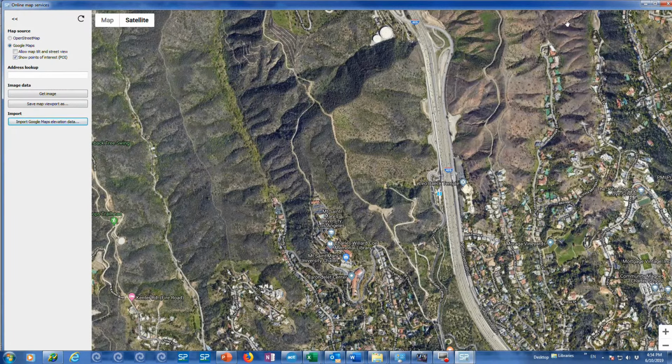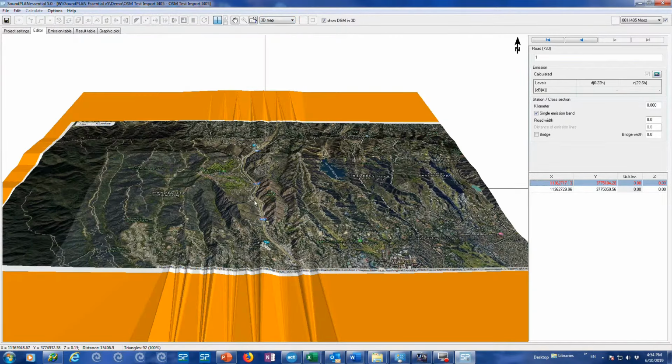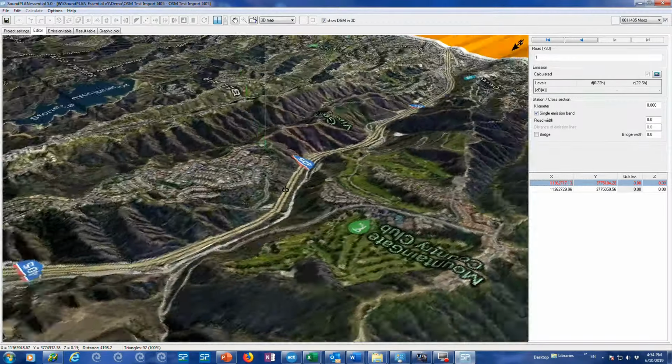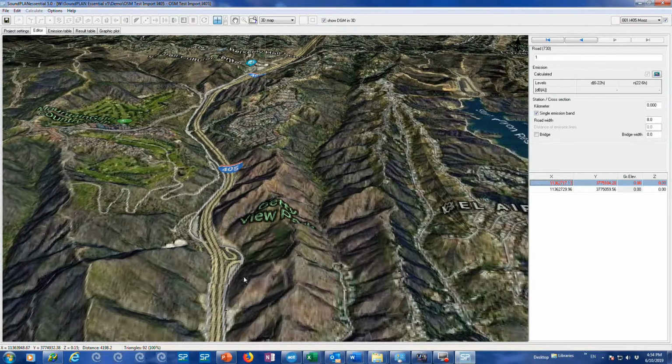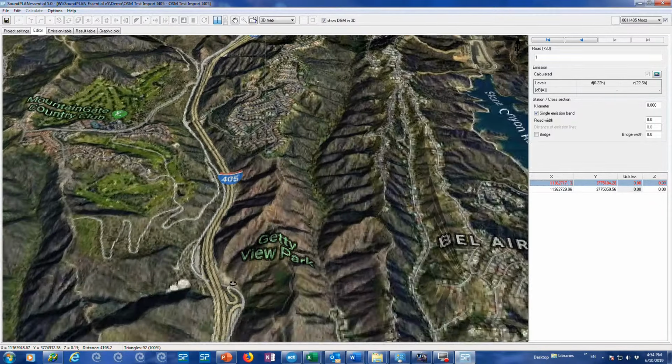And so I think this is all I want to do with the interface. At this point, if we look at the 3D map, here you can see the elevation. So the terrain is morphed, or the aerial view is morphed over the terrain. That looks good. But we don't see the roads because they're actually below that, because the elevation of the road and the buildings is right below the aerial view. So if we go underground, you can see where the actual buildings and the roads are. So we need to adjust that.